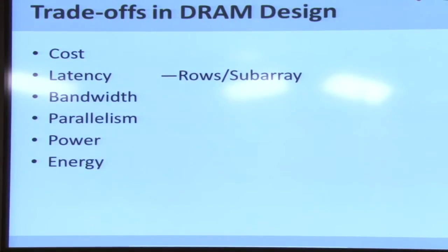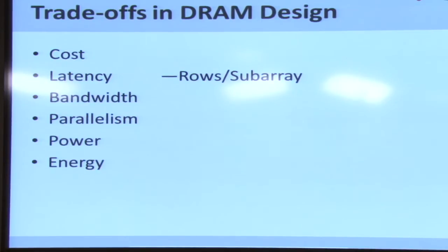Okay, so let me make one thing clear. This was the first misconception that I had. I looked at this DIMM and I thought each thing here was a bank of DRAM, but that's not the case. Each thing here is a chip, and each one has 8 banks within itself. Okay. So each one is a rank. Okay, you're getting into terminology which I don't want to get into, but it's okay. So rank. So what is your next point? No, I'm just wondering, is there a different rank?